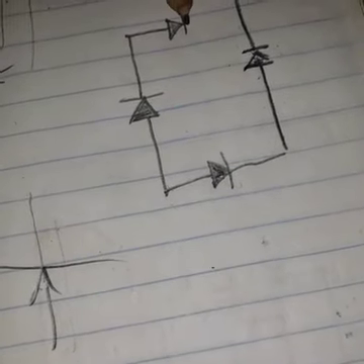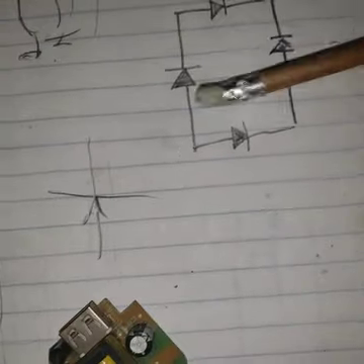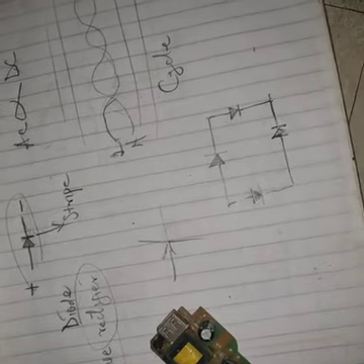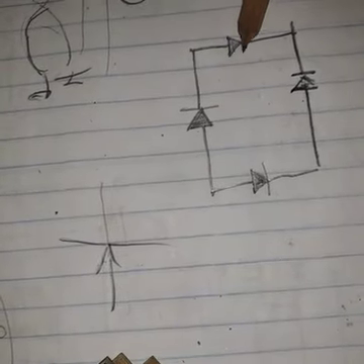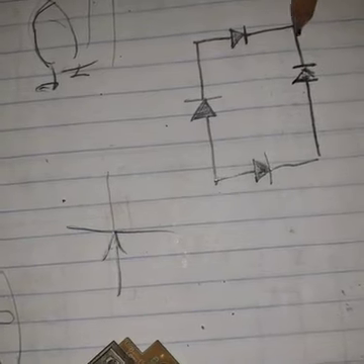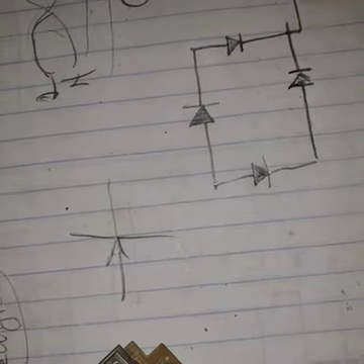And the rain has started falling here, so whatever way it is, you take it like that. Now this is the connection of how all the diodes will be together. Now, how do you know where to put your live and where to put your neutral? Honestly, it might be a little bit tricky, but the first thing I normally do, this is the negative part of the diode, the ones that don't allow current to pass through. So you just take this side out, and it will be the DC minus, the negative side of the DC.